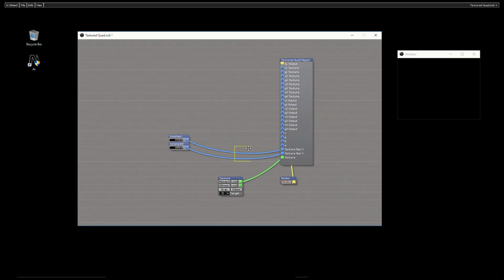A lot of these ones, the output and the texture ports, are going to use number boxes. We're going to need some faders here for RGBA, so let's get those faders in. I'm going to duplicate the text module and change its skin to a horizontal slider, then duplicate that a few times, like so, and connect that into our RGBA. You have to have the RGBA ports connected on this particular module, otherwise you're not going to see anything on your output. Okay, so all we need to do now is get in our points.